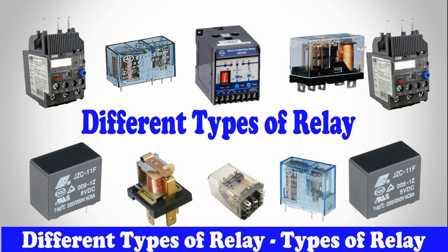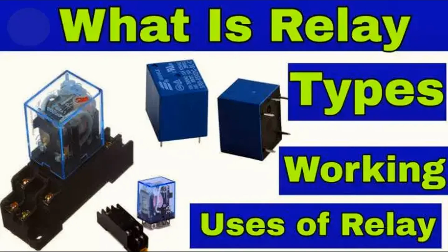In the context of relays, the input signal refers to the electrical or electronic signal that initiates the switching action of the relay. This signal typically comes from a control device, such as a switch, sensor, microcontroller, or programmable logic controller, PLC, and serves to activate or deactivate the relay based on specific conditions or commands. The input signal to a relay is usually a low-voltage, low-current signal designed to be compatible with the relay's coil specifications. When this input signal is applied to the relay's coil terminals, it generates a magnetic field that attracts or repels the relay's internal armature, causing the switch contacts to open or close.